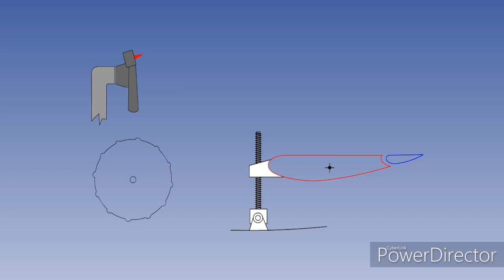Firstly, there is a mechanical brake inside the gearbox which engages and immobilizes the screw jack whenever a trim command from the flight deck is absent. This prevents the airflow from moving the stabilizer.